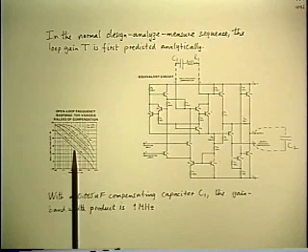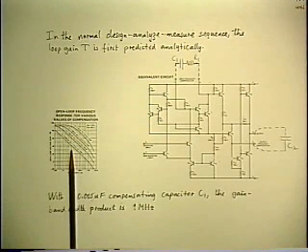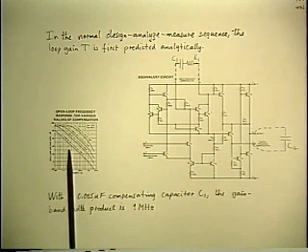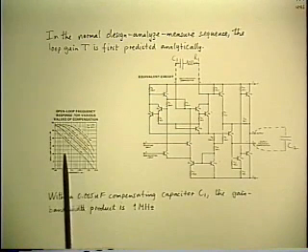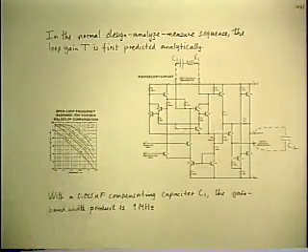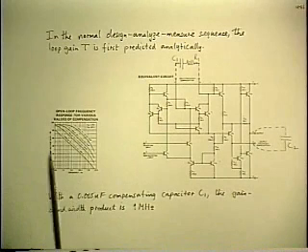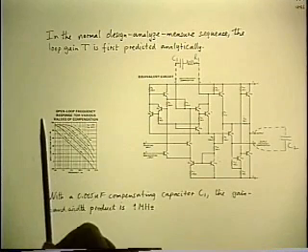Well, if you peer at it closely enough, you can see that the bottom line corresponds to a compensating cap external of 5,000 picofarads. But I'm not using 5,000, I'm using 100,000. Well, that's no problem, because obviously I can just scale this according to the factor representing the capacitances, because it's that capacitance that simply moves this low-frequency pole down in proportion to the value of capacitance. And then even in the graph they give, the pole is moved off the picture below 100 hertz.